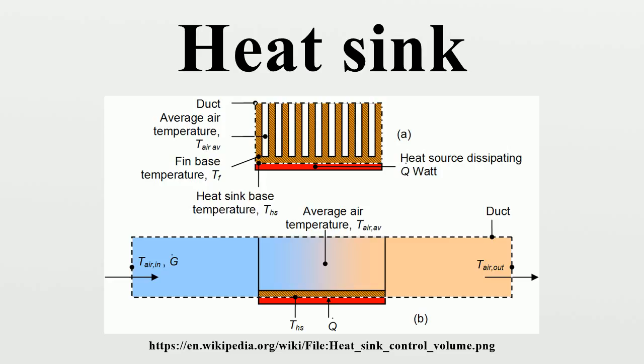The emissivity of a material is tremendously frequency dependent, and is related to absorptivity. For most materials, the emissivity in the visible spectrum is similar to the emissivity in the infrared spectrum. However, there are exceptions, notably certain metal oxides that are used as selective surfaces.